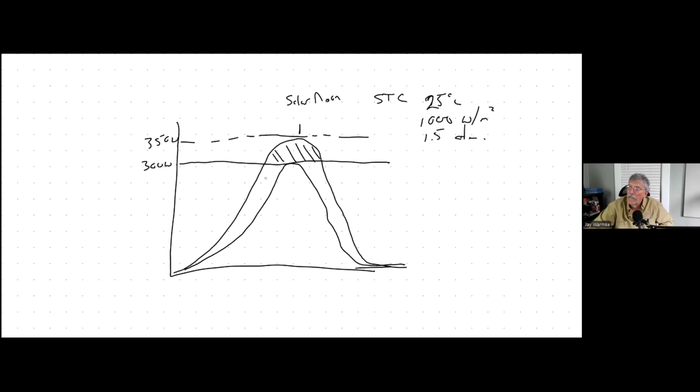And I am not going to capture this if I put the smaller panel in. So this amount of power will be lost by having the bigger panel. Even though I'm clipping off this bit, I'm generating this much more power because I have a bigger panel. And because of the cost differential between solar panels and inverters, it turns out that an inverter load ratio of like 1.3 to 1.4 is generally going to be the most economical ratio that we're going to be dealing with, solely because panels are a lot cheaper than inverters.